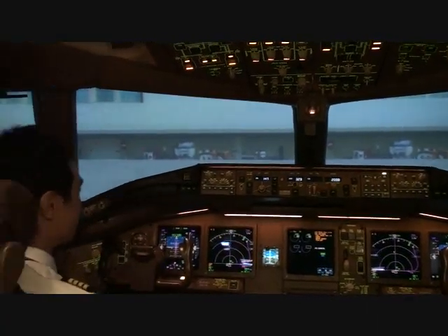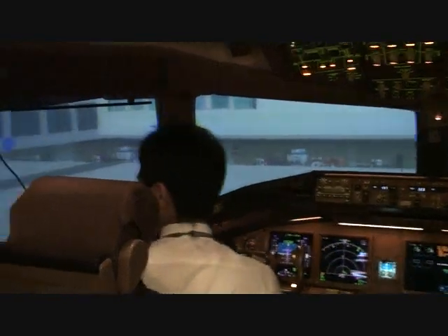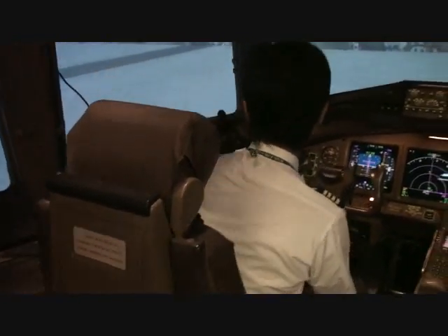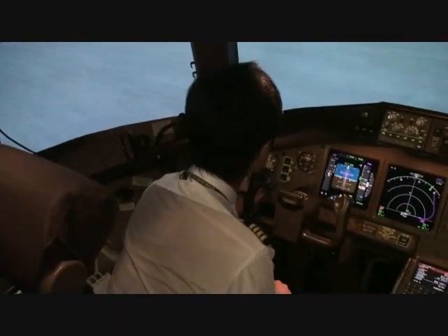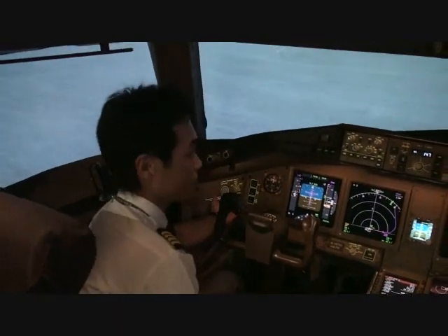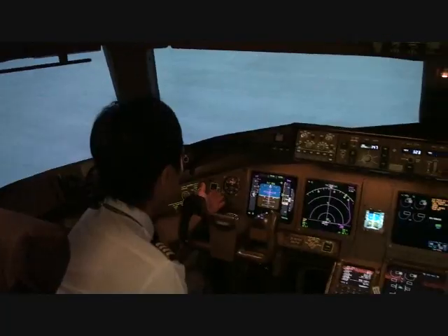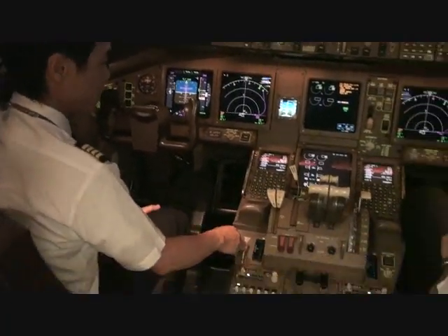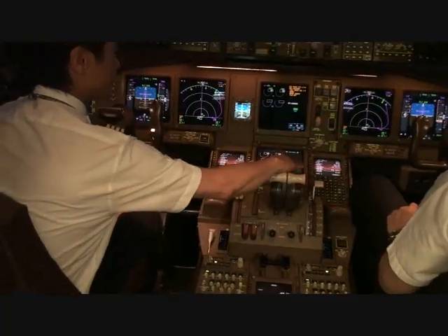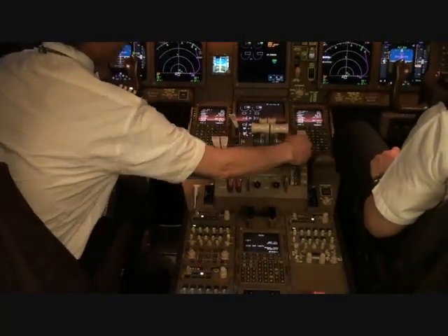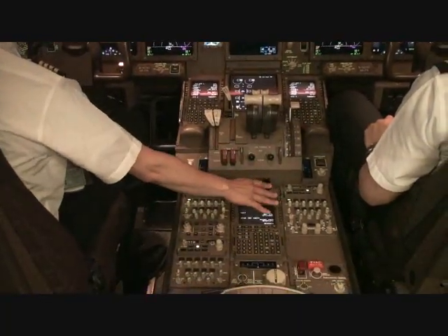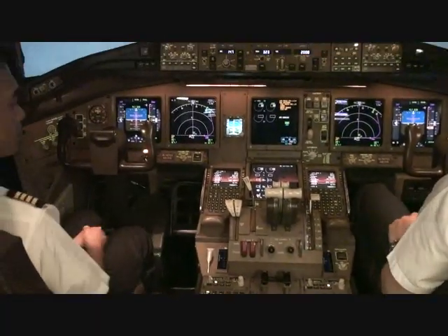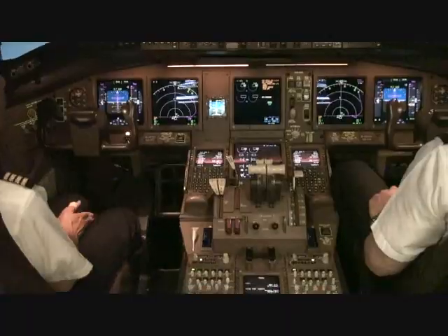Then over to the oxygen panel and around again across the front of the flight instrument panel, and then down over the parking brake and across the engine controls to the flap controls and the alternate flaps. Coming back to the fire switches.